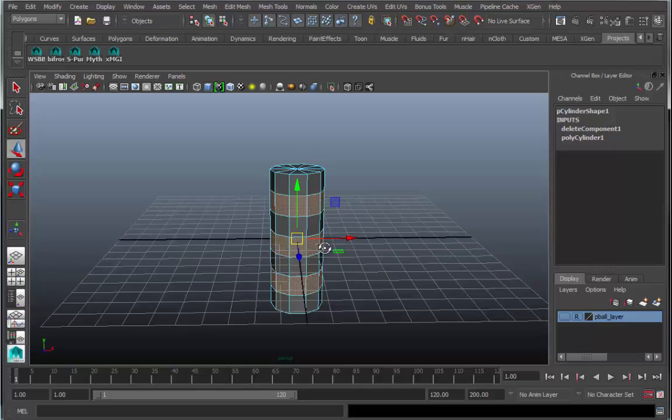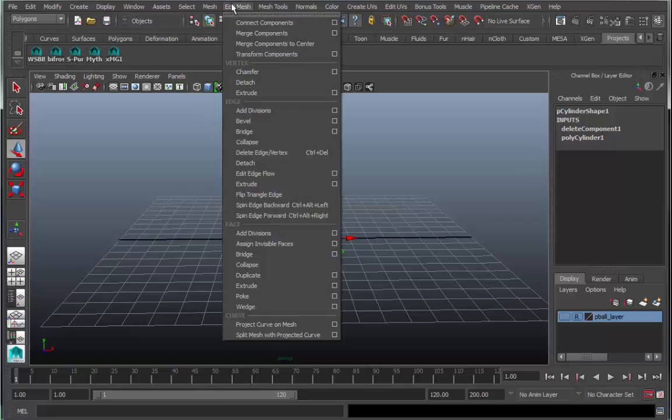And we're going to indulge in something that we have not done thus far, which is we're going to use the default extrusion tools. Remember, every time we've done extrude thus far, we do not use the controls that Maya by default gives us because they align things according to each of the selected objects or selected components' normal orientation.